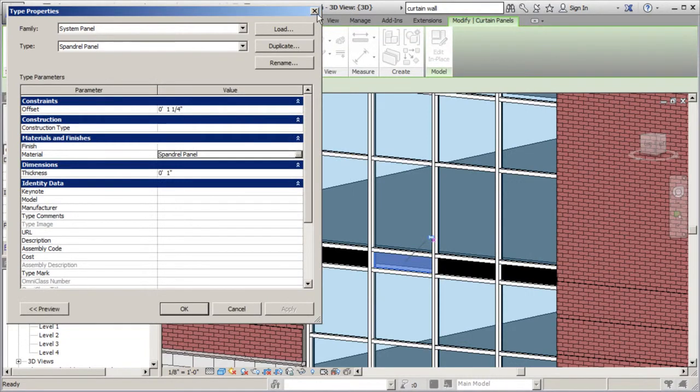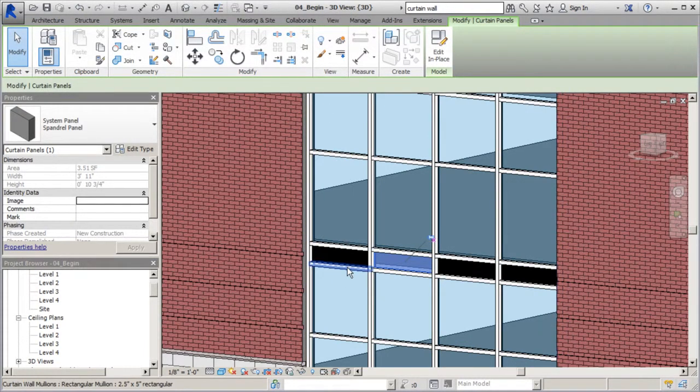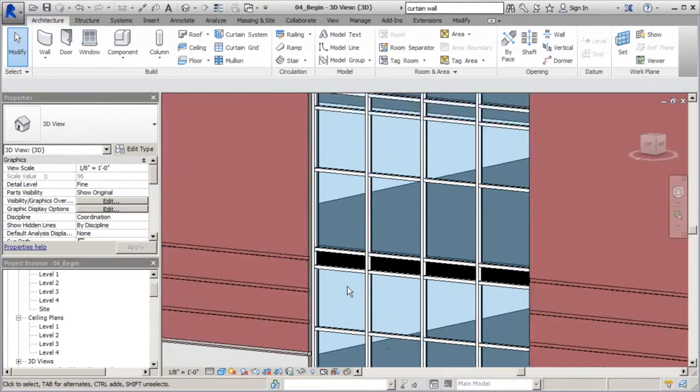So the key is, if you know how you want this design and layout, go ahead and make all your changes, place the panel where you want. Then you could go to the areas in between the mullions or in the grid pattern or whatever, and you can then take the panel that you made all the changes to, that you created, that you spent all the time with, and all you're doing is selecting, unpinning, and going to a drop down to flip out the type of panel. So it's really helpful stuff.